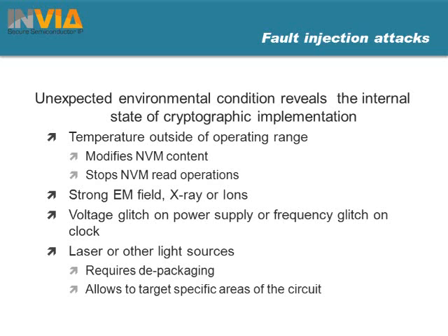Voltage glitch is definitely a very famous and probably the easiest way of mounting a fault injection attack, because it doesn't even require any privileged access inside the chip. So a voltage glitch on the power supply or a frequency glitch on the clock.